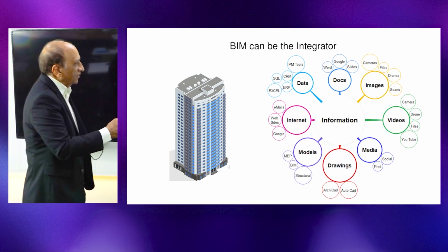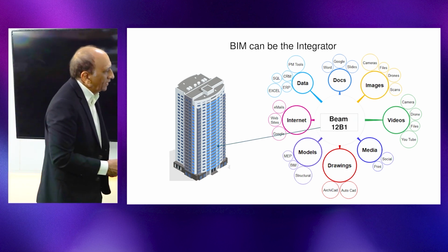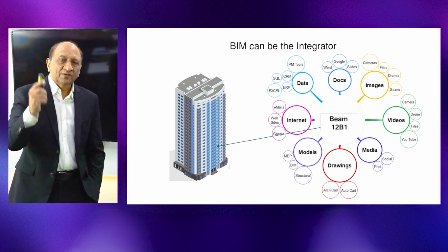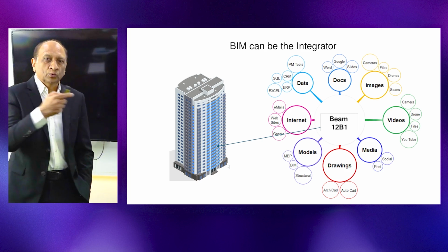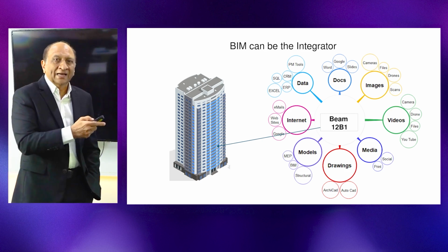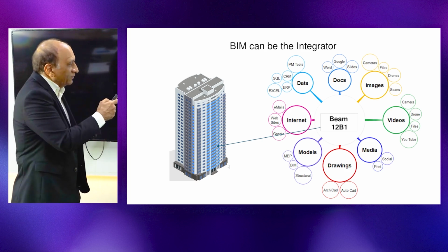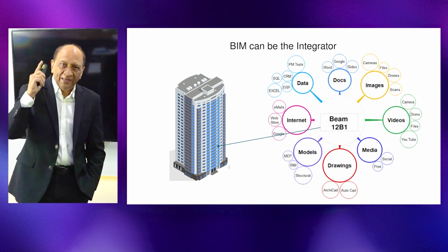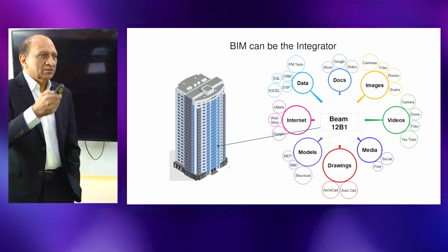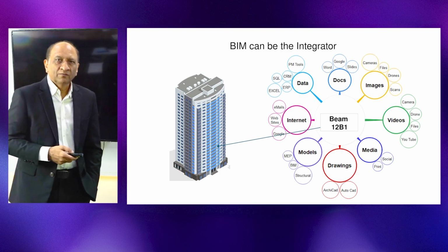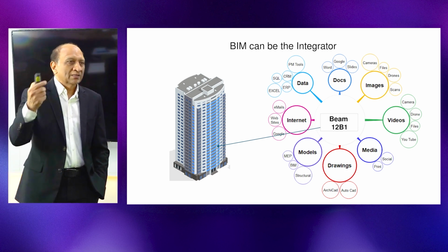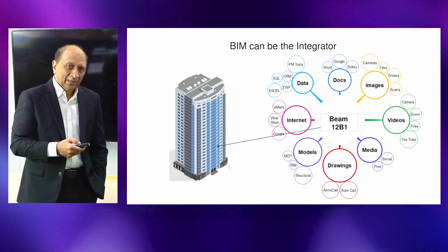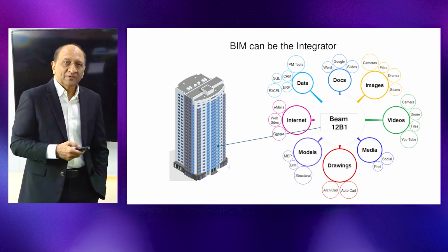If we take all that information, for example, about what has been done on this building and attach everything to that beam, then we have a physical connection of the information to the physical BIM, and we can store all that in references or whatever system, so that for this beam we know what has been done right from the beginning until now. About painting, about cracks, about its visibility, or somebody draws something on it, all the information can then be referenced back into the BIM model and into the BIM system.